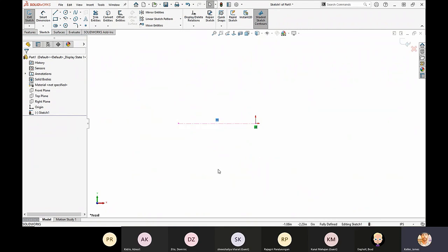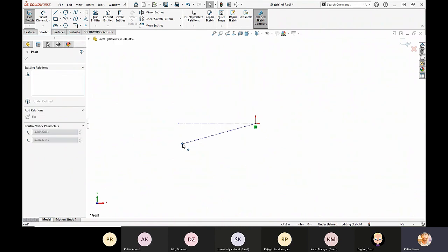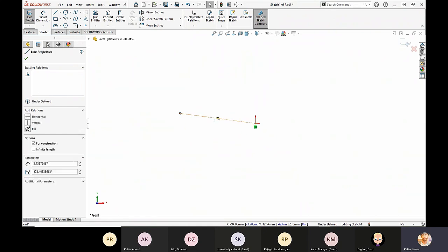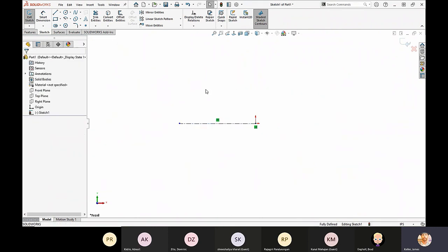If I had not done that, I can select that, delete it, and now you can see how the rest of the line turns blue, and I can now drag it outside of horizontal. So if I wanted to add that manually, no problem, I can select it, and then in the context menu, just choose Make Horizontal to make it as quick a change as possible.